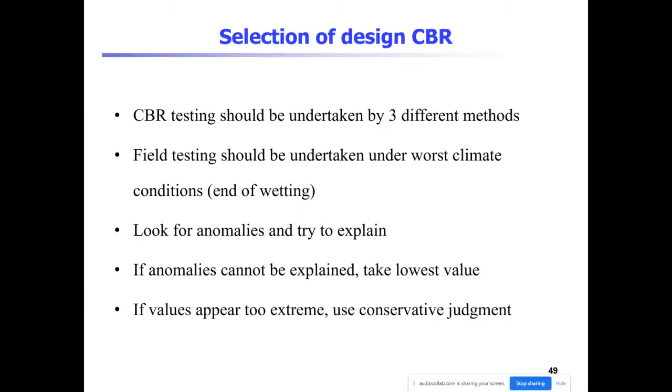These are some rules and some hints for determination and selection of design CBR. So the first rule is that in order to calculate the CBR in the field, you need to conduct at least 3 different testing methods. So CBR testing should be undertaken by 3 different methods.